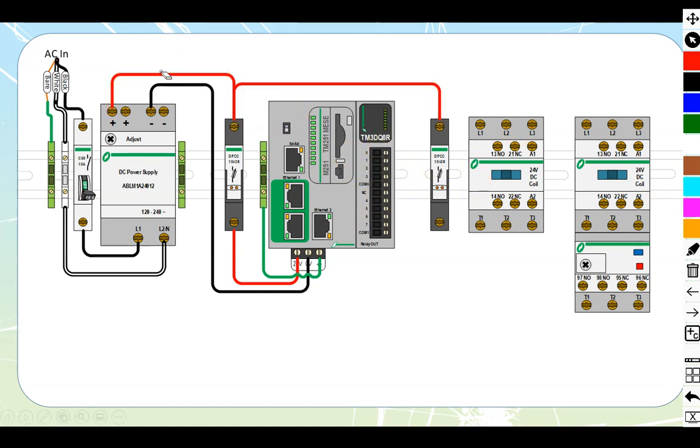So that's our supply of power that we have into here. Let's start with our wiring. Now, we said that we were going to be using sourcing, which means that we have to come from our fuse holder to our common. So we're going to go and do that. We're going to come from here, and we're going to run to our common.